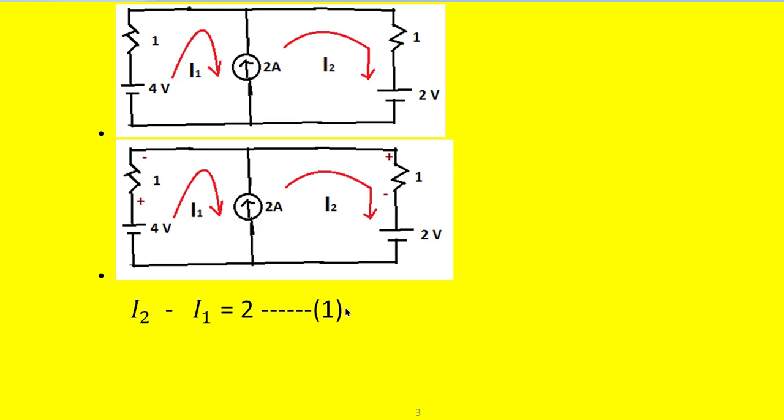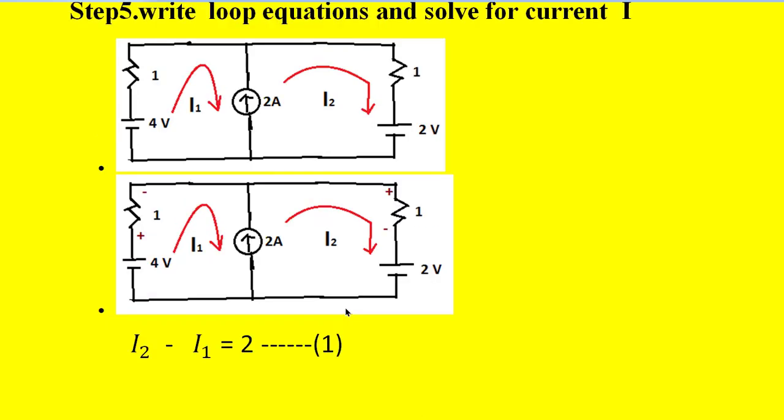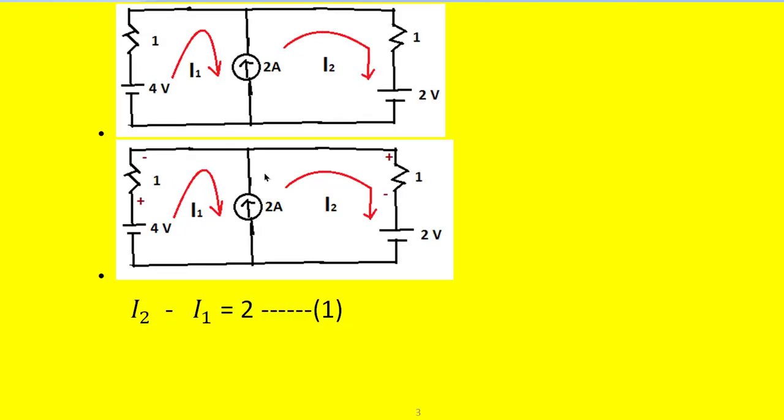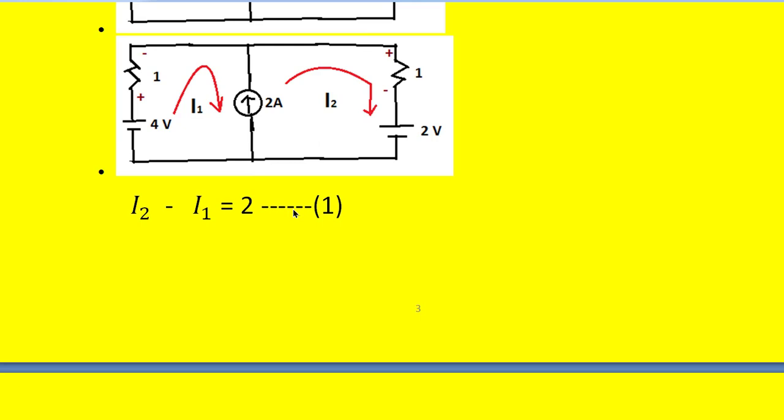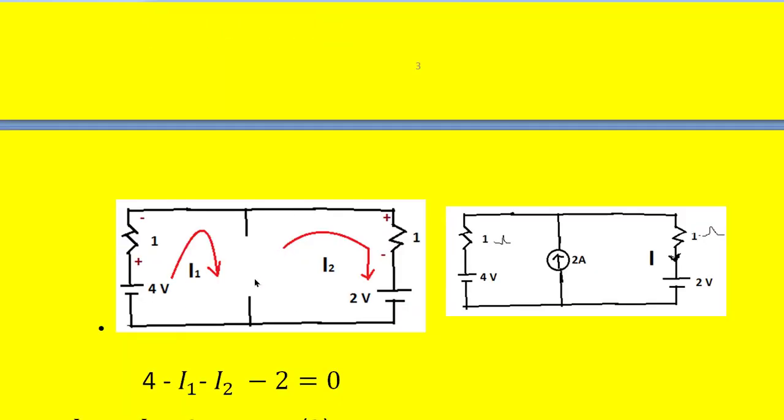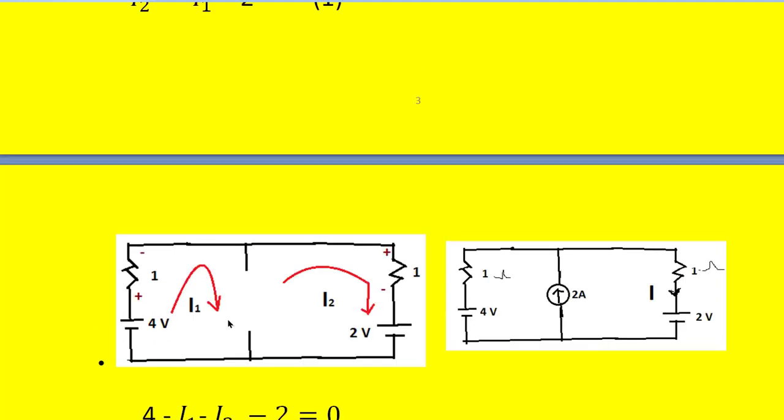Then step 4 is, we have to remove this current source which is there in the circuit, which is in common between the two loops. Once we remove that, we get the circuit like this. And this circuit is called the mesh circuit. Remember here, though all the elements are in series, we are maintaining the previous current directions and previous current values as they are, and polarity also.